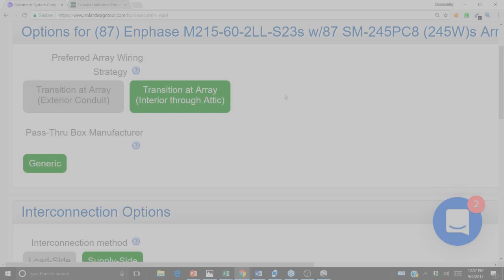And furthermore, there's another part of code that says, hey, if there's moisture in the air outside your house and then you have a drier air conditioned space inside the house, that difference in moisture alone is going to cause the higher pressure moist air to be kind of going into that conduit and then condensing.